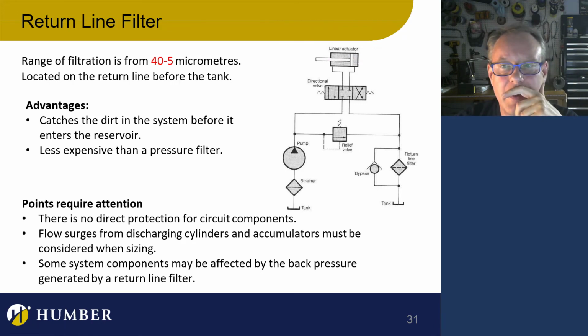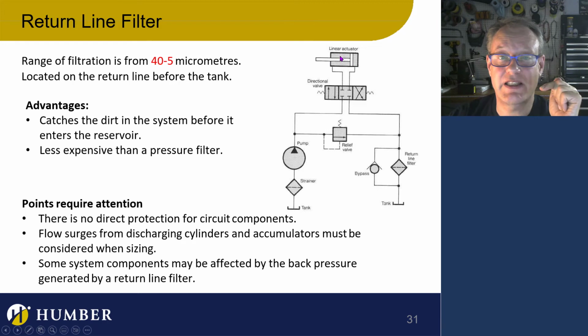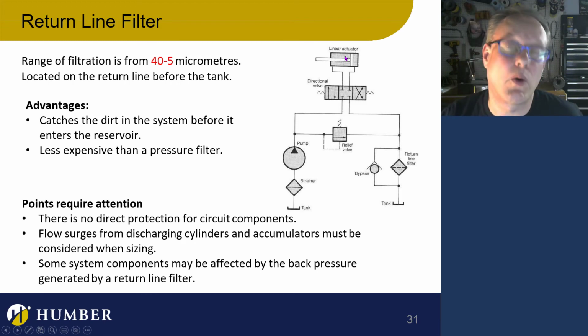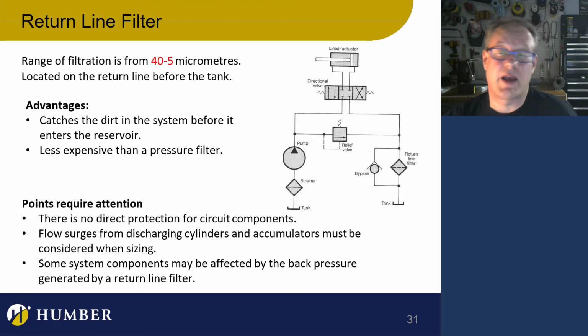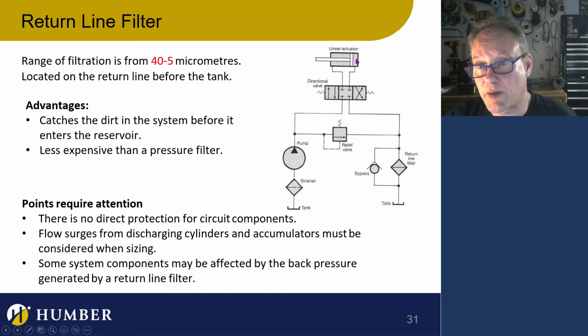What I mean is that if I were to find that this side was generating 100 psi because of the back pressure here, that would be seen on this side as higher pressure. So it would actually be more than 100 psi, and that's because of the different sizes on either side here. So if I wanted to generate 100 psi here, I'd have to actually put more pressure here to generate that. I hope that makes sense.